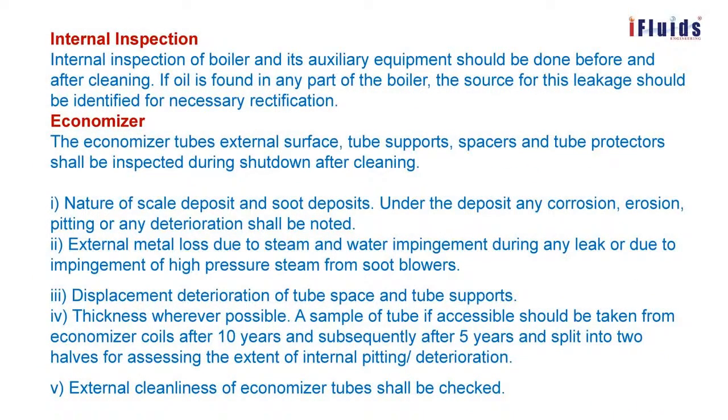Internal inspection of boiler and its auxiliary equipment should be done before and after cleaning. If oil is found in any part of the boiler, the source of the leakage should be identified for necessary rectification. Economizer tube external surface, tube support spaces, and tube protectors shall be inspected during shutdown after cleaning. Nature of scale deposits and soot deposits. Under the deposits, any corrosion, erosion, pitting, or any deterioration shall be noted.